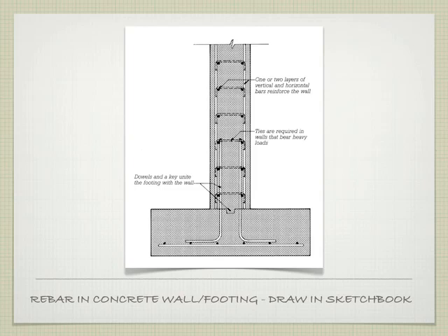Usually you're going to embed some kind of a 2x4 or a piece of wood that will then be in the concrete after you're done with the pour and the concrete's been allowed to cure. You go in and remove that piece, and it can be fairly quick. You don't have to wait as long as you would have to wait for the bulk of the formwork. You can pull it out within 24 hours usually, and it will keep the bulk of the shape, because it doesn't have to be perfect. It's not a finished piece.